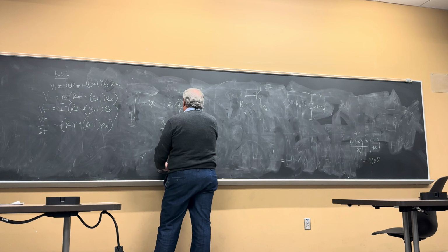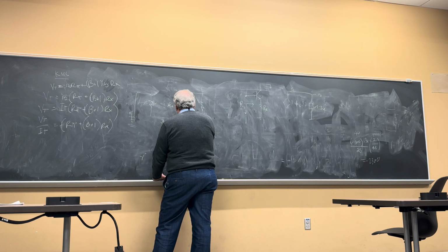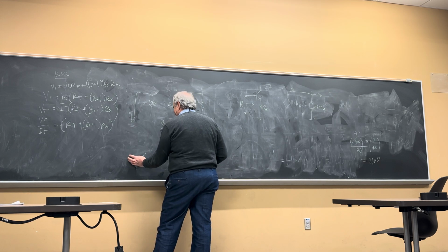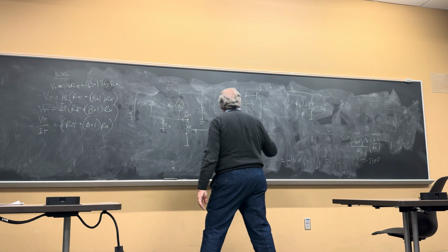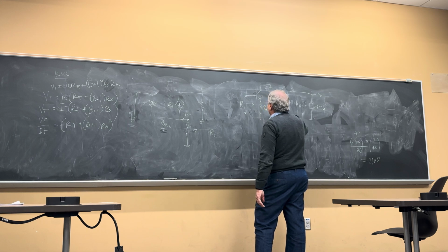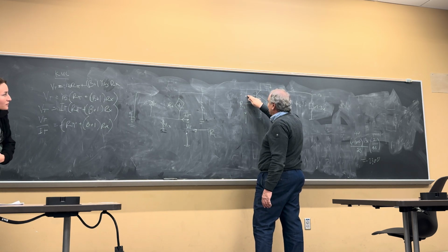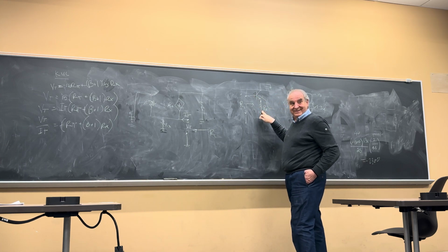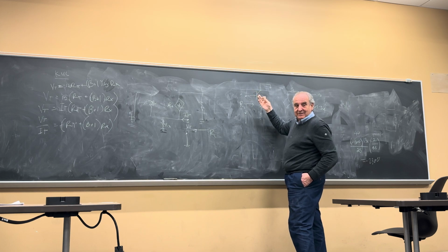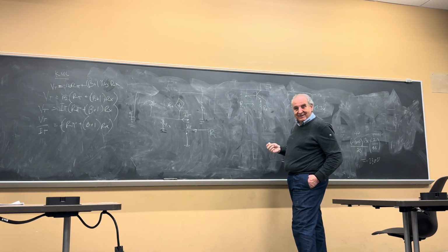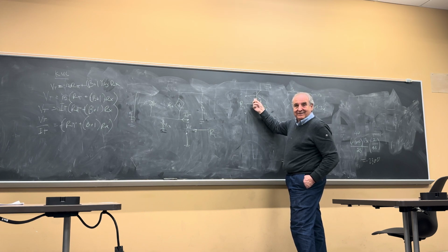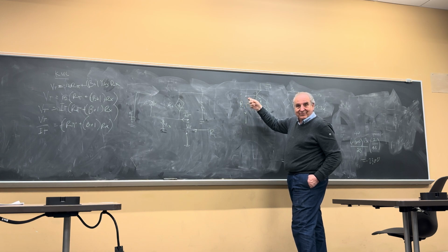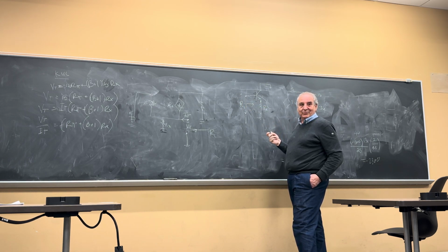Here's what we're looking at. Rn this way, there's Vt, and there is It. We're looking now at the transistor in this direction, from there to there. And what do we see? Looking from this way, we saw R pi plus Rx times beta plus 1. Now looking up the emitter, what do you think you're going to see? You're going to see Rx in parallel with the little Re, because this has little Re to ground. With the T model, it's very quick. With the pi model, it takes a little bit more work, but it gives you the same thing.